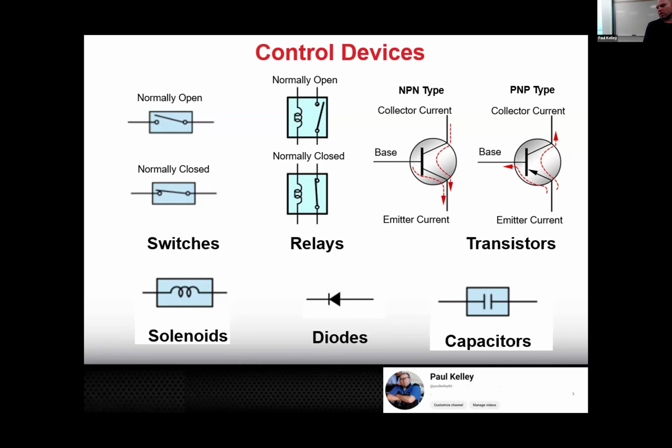But what I would need to do typically is go in with a scan tool, and I could go into active test, special functions, some special menu, and then go like control the fuel pump, turn the fuel pump on, click. When I tell the scan tool to tell the ECM to turn the fuel pump on, what it's actually doing is it's talking with the ECM and saying, hey, give a positive right there on that base. So if I want to test it, I got to tell the computer, turn that fuel pump on, which means the integrated chip is going to give a positive right here.